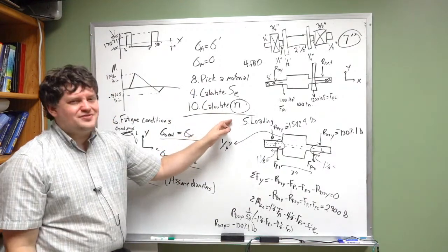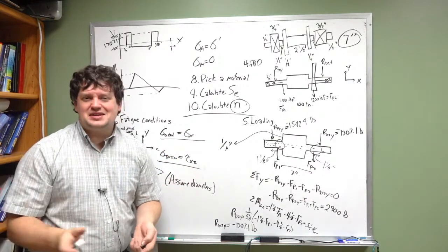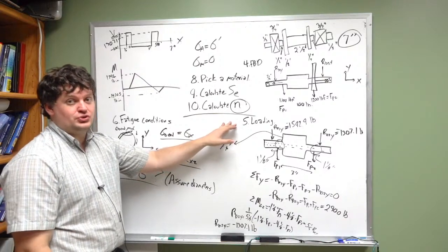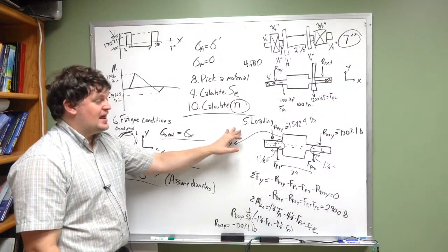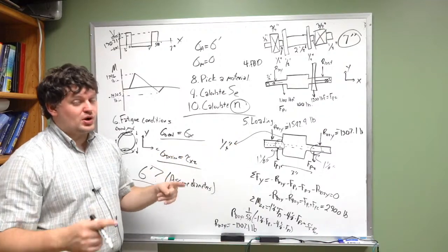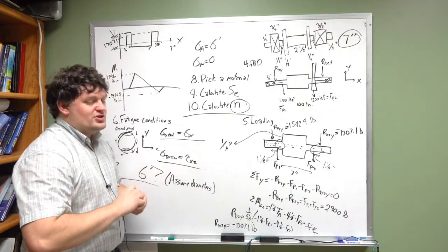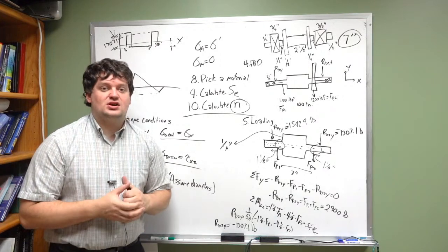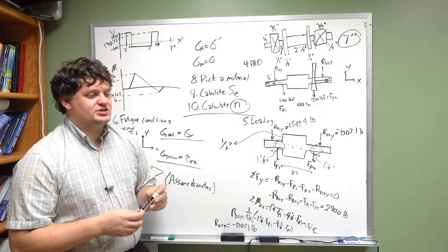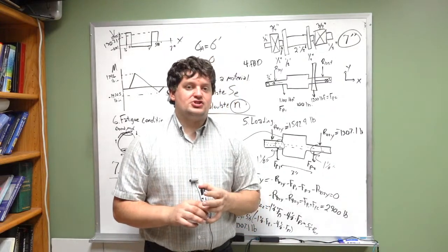You do not want to have an N value close to 10. That's bad. It shouldn't be 10 or above. I want you to try to aim for 2. If you can get an N value of 2 or really close to 2, it shows that you went through the proper design process. Okay? If you have any questions about this, we can talk about it next week in class. Next week we're going to be covering different material, but that's all that I have for shaft design.